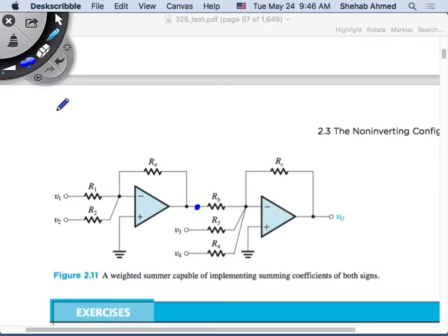I cannot put a positive supply and a negative supply in parallel, because current will flow. So if I put this and this in parallel, the currents will not sum up here, right? They will circulate between them only, right? So I cannot put a positive input and a negative input in parallel. So let's say now I put a set of positive inputs here and a set of negative inputs here, for example. So the circuit, we'll apply the same superposition that we discussed.